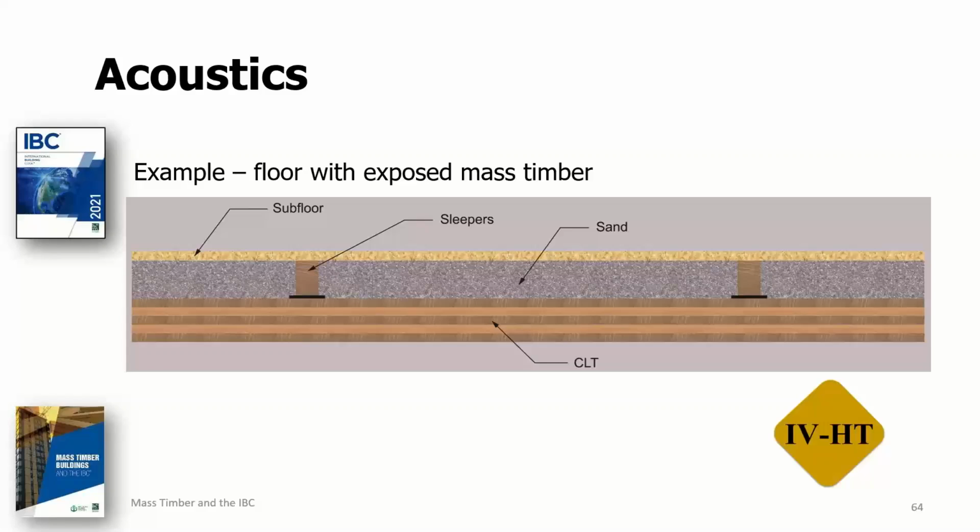One of the characteristics of mass timber is that it has a high strength to weight ratio when compared to other panel and slab type construction materials. It weighs significantly less than, say, a concrete slab of the same thickness. With acoustics, more mass typically means better noise control.